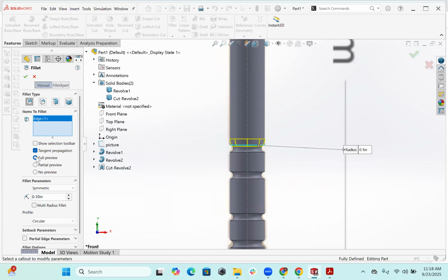So we don't see the inside, but if you're fitting something in another piece, I'm gonna hide this part so I can see that. You definitely need to also round this off so you can fit this piece into the other one. So I'll go to my last fillet and I'm gonna edit that because that was this end, right? So I'm also gonna do this end. There's gonna be the same curvature. There's no need to create a new fillet. All right, now this piece is done.